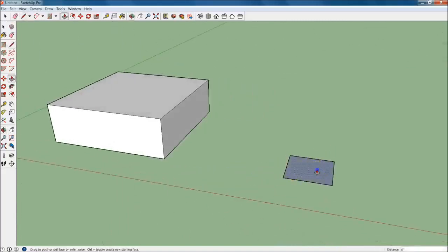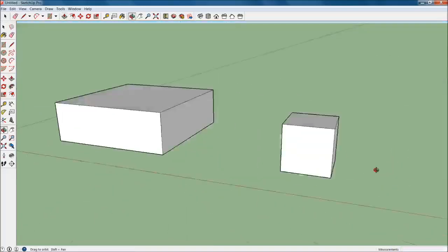All right, now we're going to come up. So I'm using my shortcut keys. Whoa, teaching a tutorial. Okay, go back over here and hit your push-pull tool. Click that again. We're going to pull that up 10 feet. So click right there, go ahead and release it, and I'm just going to type 120 now because 120 inches is 10 feet. Boom, there you go. So 10 feet.